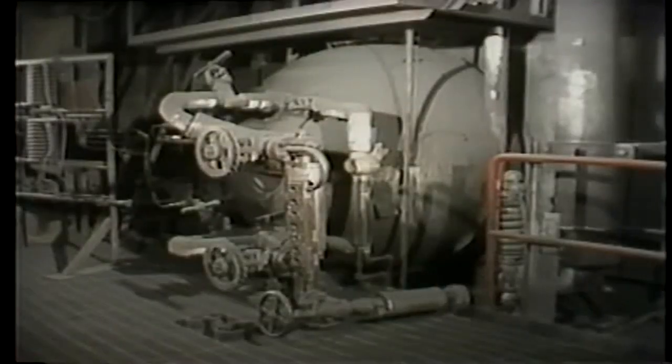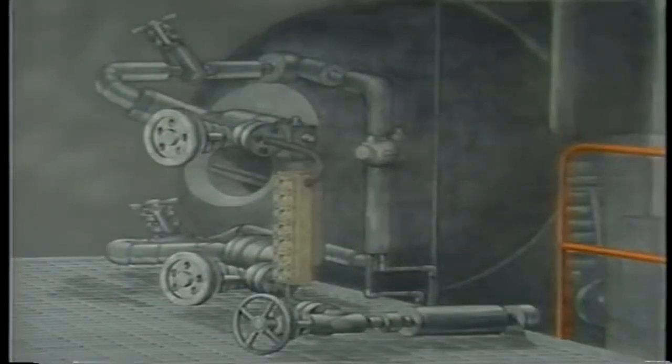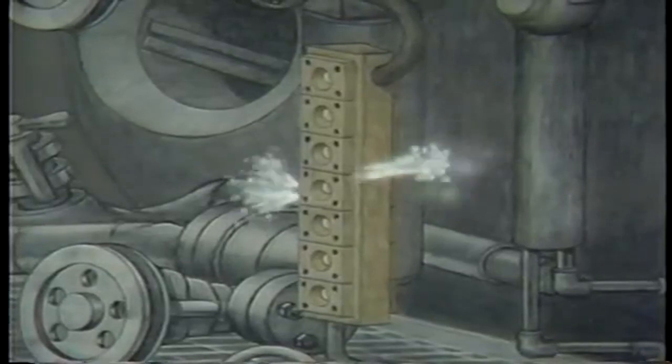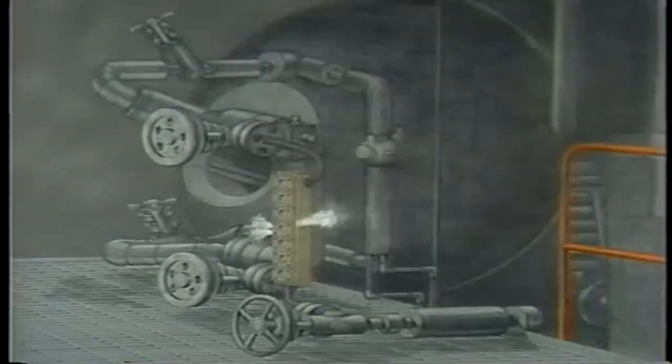For example, most boiler drums have gauge glasses like this that can be used to check the water level in the drum. Due to the tremendous pressures and temperatures that a gauge glass is subjected to, leaks may develop. In most cases, the amount of water that leaks out of a gauge glass does not affect the operation of the boiler. The operator may choose to live with the leak until the boiler is taken offline for scheduled maintenance,